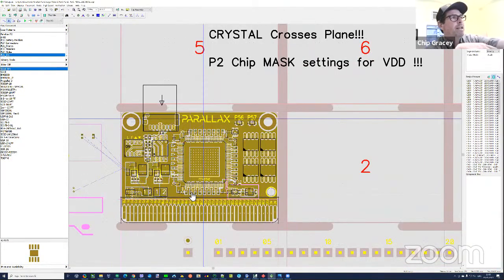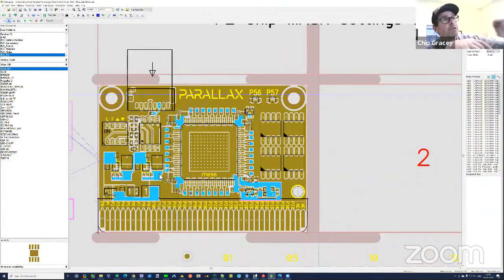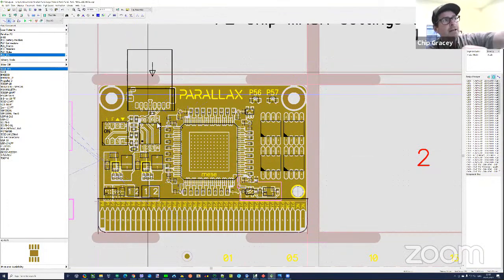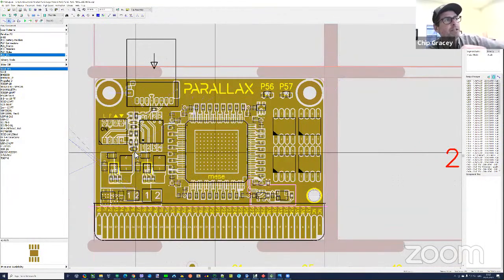So by getting rid of the crystal, which slewed very slowly, and putting in a nice sharp crystal oscillator with a 3.3 volt inverter, it's going to deliver nice sharp edges into XI. And so there's not going to be opportunity for these upsets anymore. Great, thanks.